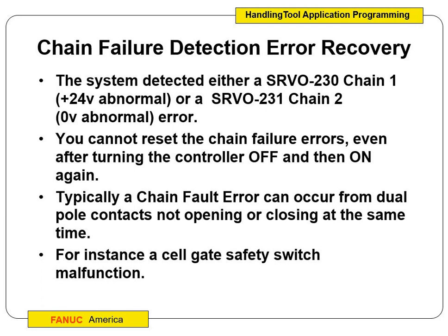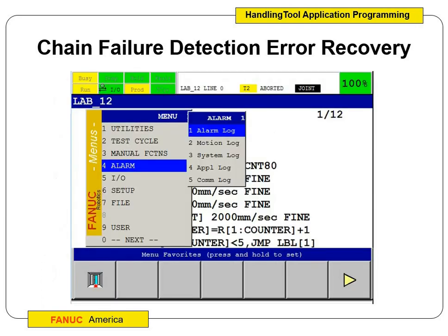So when we move one of the robots down to the gym for the incoming freshman orientation or something to show off the program, if it rattles too much as we're going down the sidewalk, the sensors become a little loose and don't stay aligned, so we get a chain error. So we have to find out which sensor that is, make sure the door is closed, or whatnot.